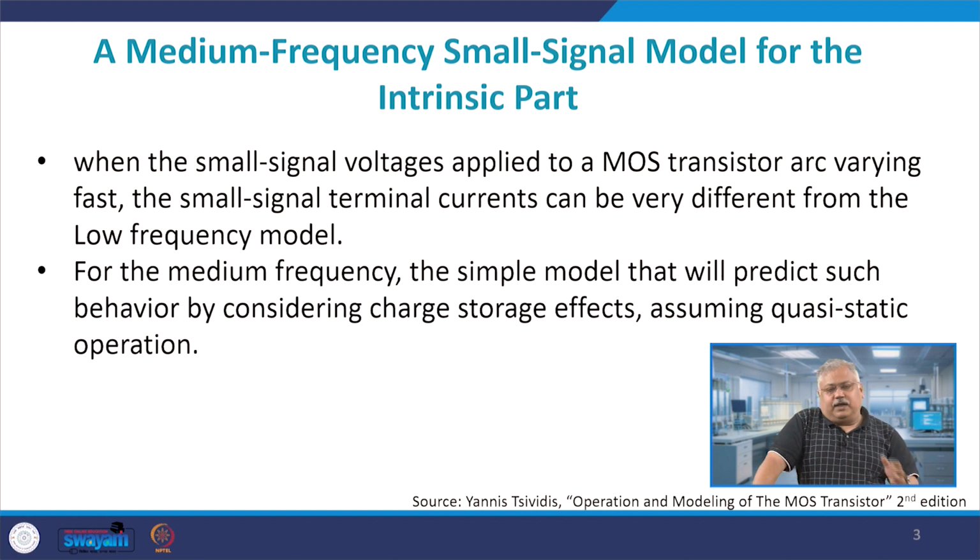Let us suppose you have a number of charge carriers available. You are giving on the gate side a signal which is very high, of the order of a few gigahertz, let us say multiple gigahertz. It effectively means that the charge carriers in the inversion layer should be able to respond to that frequency, because there is some transit time. You can understand this when you give a positive pulse and a negative pulse: the electrons are attracted towards the positive pulse and repelled from the negative pulse. Now, if this positive and negative pulse are varied at a very fast rate, the electrons will not be able to react to the changing electric flux, and therefore they will stay where they are. Whereas, if the frequency is small or medium, a small amount of the electrons will be able to respond to the change in the value of the electric field.